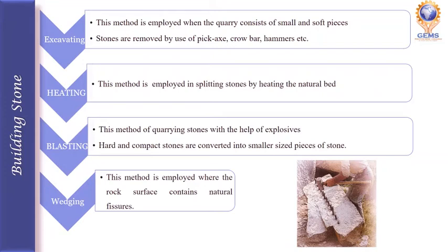First we have to bore a drill hole to inject the gunpowder, and we have to charge that gunpowder and we can fire it. Once the rocks are blasted, the big rock will be broken into small stones.